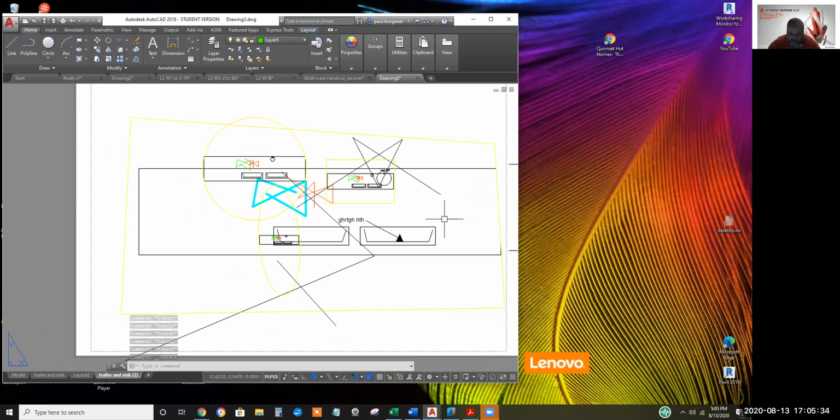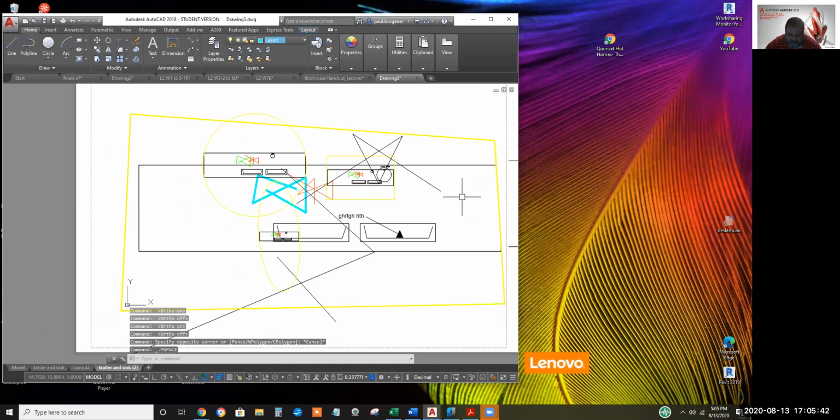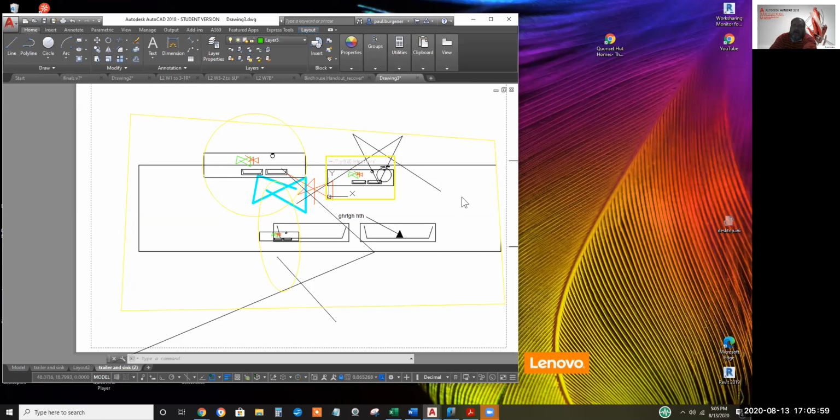I think it's Control L. There we go. Control R lets you toggle from viewport to viewport, I assume in the order that they were created. So you can activate a small viewport within another viewport.